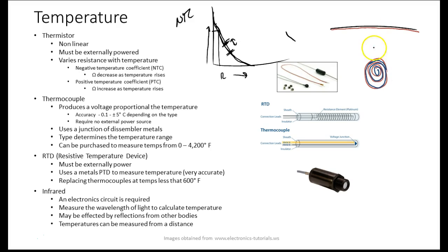It would cause this tip up here to move, and then we'd come up here, and they had a mercury switch up here that we used one side for heat and the other side for cold. And when it's cold, it would contract and it would go into more of a helix, right? You understand that? And when it tilted over, it would cause my heater to turn on. On the other side was air conditioner, right? You ever seen these old thermostats? I got one over there in the other class.